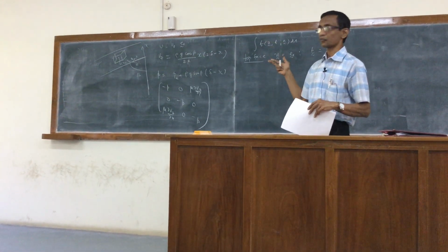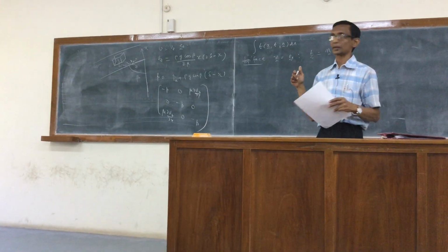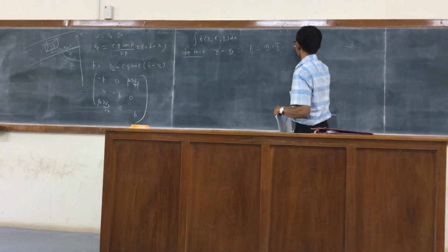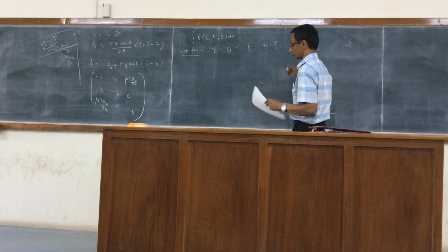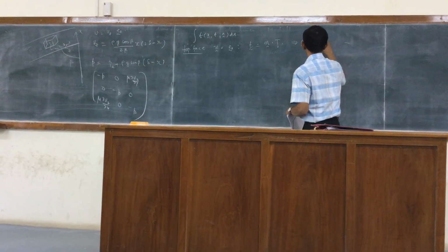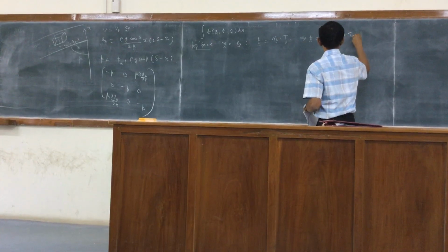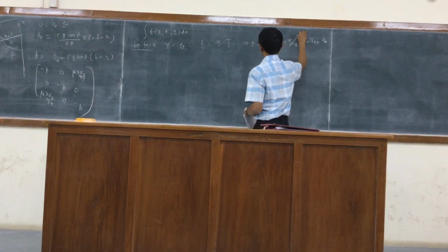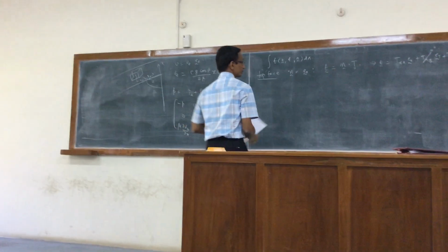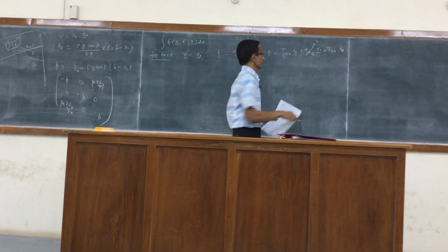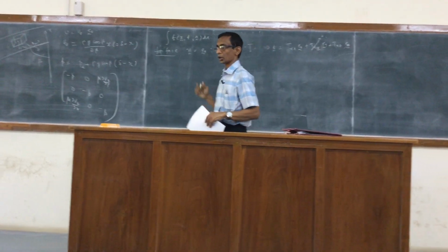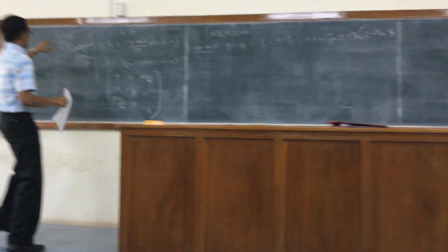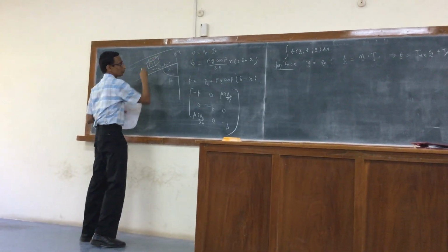So given the velocity profile, we can easily calculate mu times dv_z by dx. So this is how we will calculate. So that n is equal to e_x, we saw that the stress vector would be minus p e_x plus mu dv_z/dx e_z. So it has components in both directions, e_x as well as e_z. This will be the normal force, and that will be the tangential force acting in the z direction on this top face. We just take the top face.